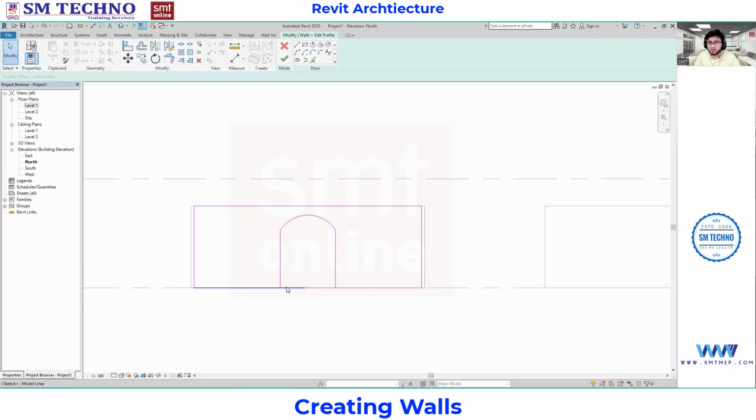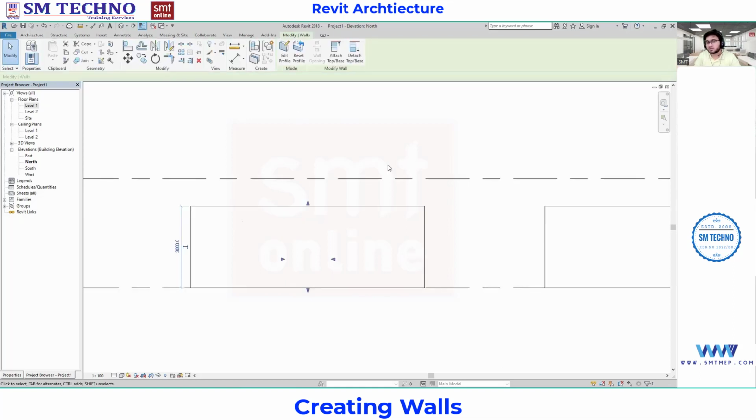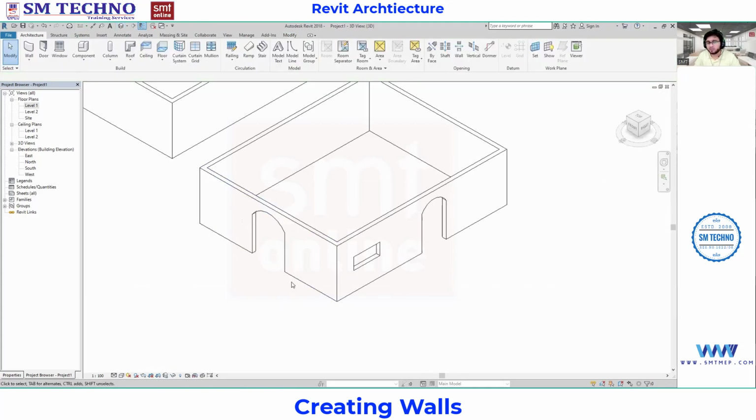Now here, if you don't know the trim, just select, drag and place. You can also place the bubble from here to here also. And place the bubble from here to here also. Professionally is to go with the trim only. So can you see this is continuous now? Now it is going from here to here, again from here to here. Now the profile has been done. Click here, finish. Now when you open the 3D, in the quick access toolbar, you will get the 3D. So here you have got the opening for the wall.